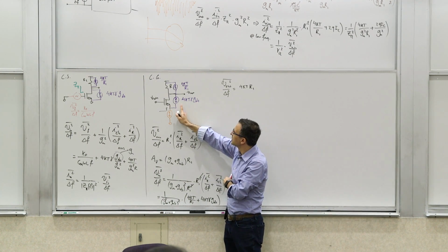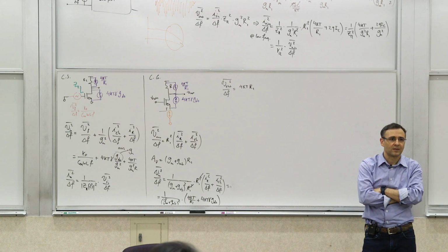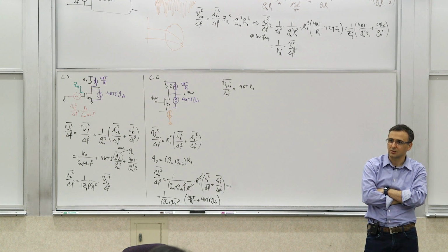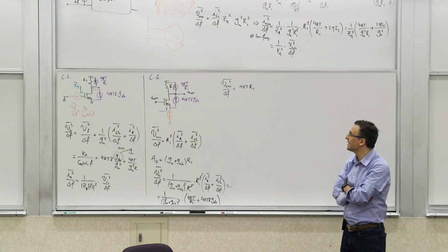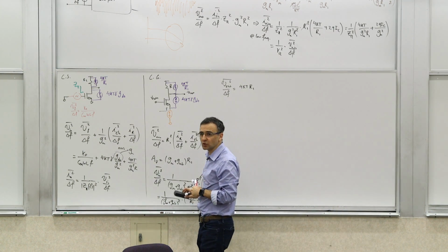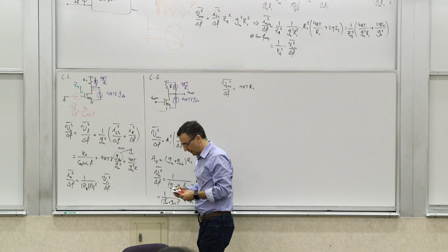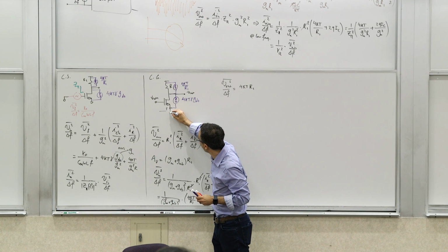Does anything change from the perspective of that noise source? What we've done is change that orange source, that equivalent, from a voltage source to a current source, which means we've changed the source impedance from 0 to infinity. So if you null that, what happens? It becomes open, not short. So if I have an open circuit here, think about this. It's an open circuit here. So this is open.